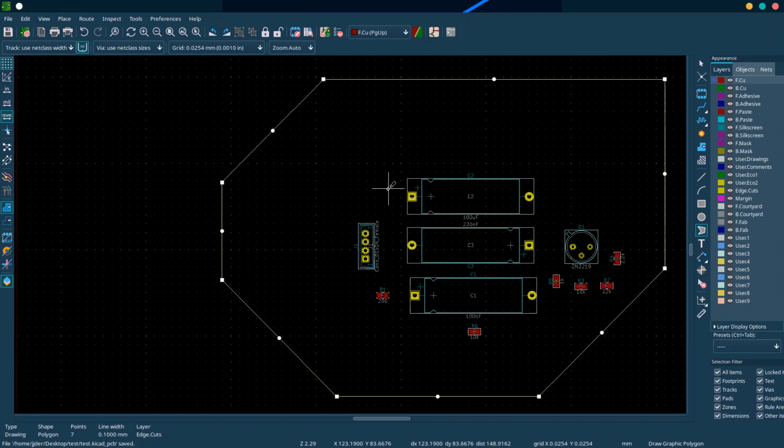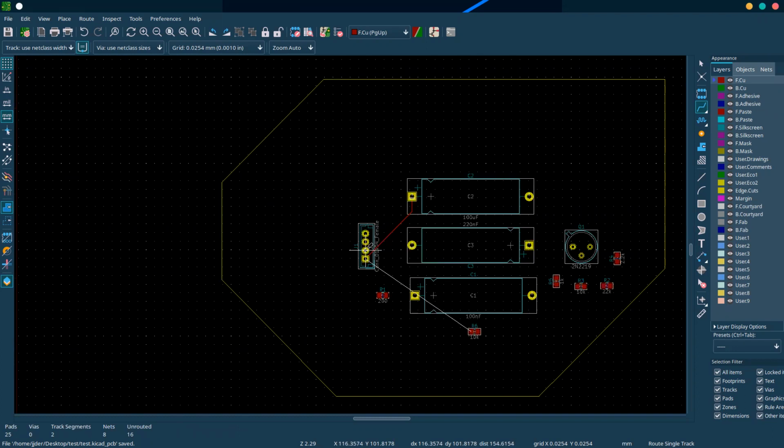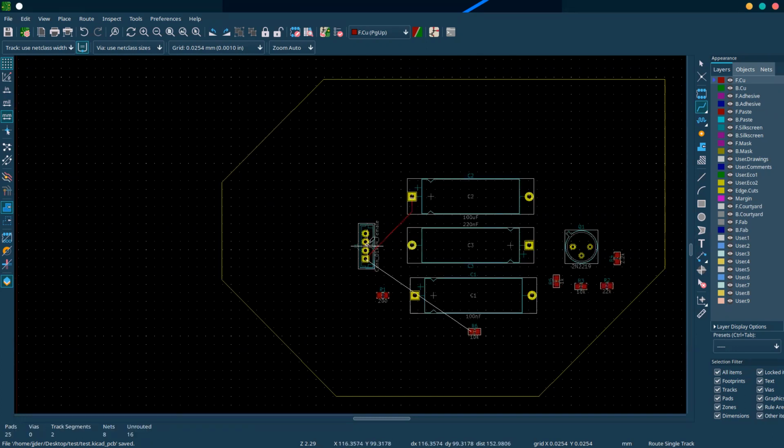If you recall in the schematic editor, to lay down a wire was W. It obviously translates that would be X in the PCB editor. So to lay down a wire, you hit X over a pad, and you can see because of the net list, it tells us exactly where this wire needs to connect to. It knows that this connects to that because of the net list. So now you just go around and you hit X on everything and you connect things together.